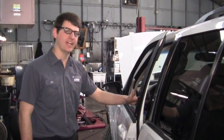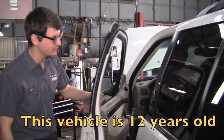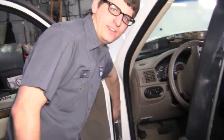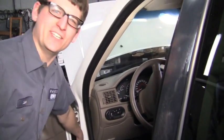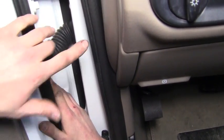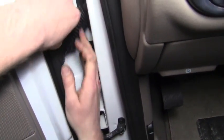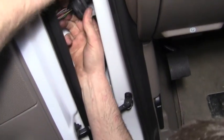We're up here at the driver's side door, and over a period of time, years and years of this door opening and closing, the wires that are in this loom, in this harness, where the door pivots, get pinched over time. So this is the first place we're going to look and see if we have any damage. What I want to do first in inspecting these wires is try to remove what I can of this cover. Now, we should just be able to pry it out from the door. And we're going to pull it back and inspect the wires.